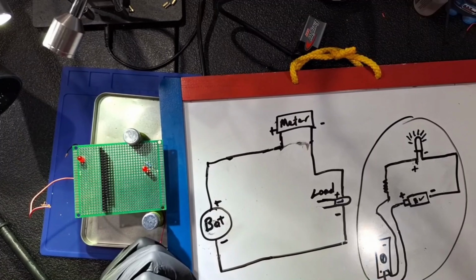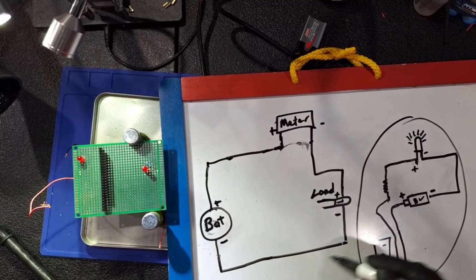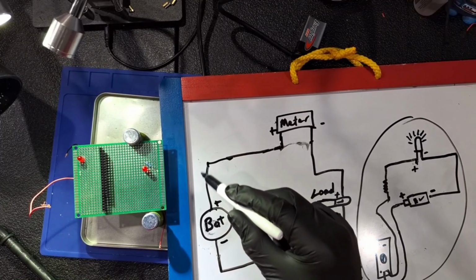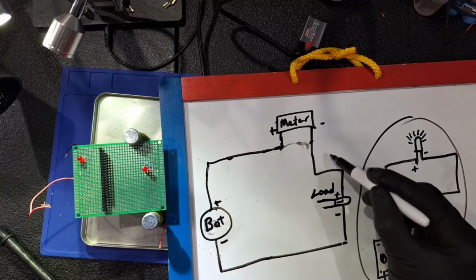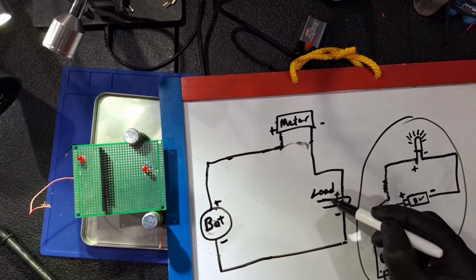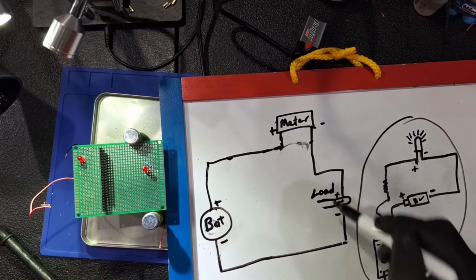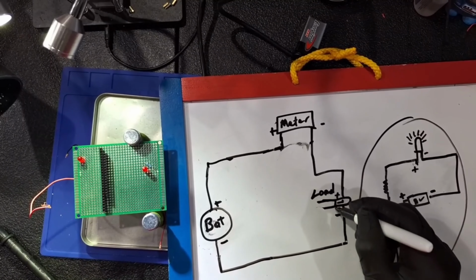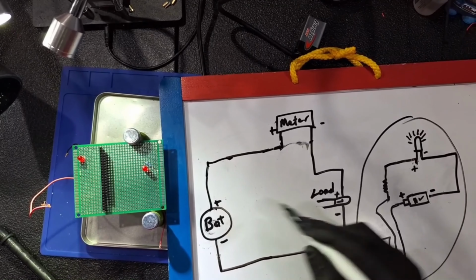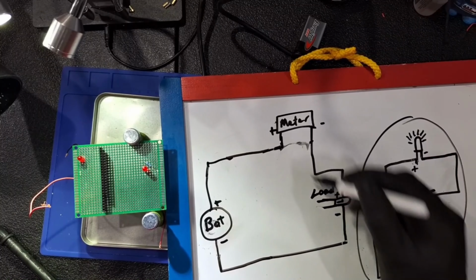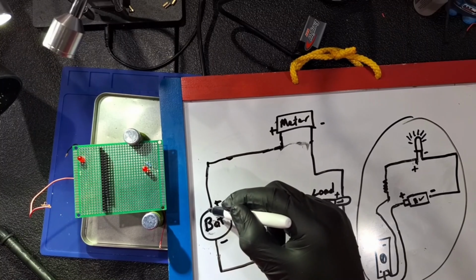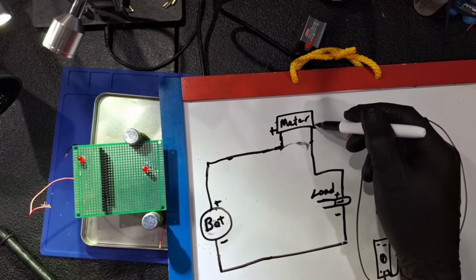And this is what was confusing me, mainly because of color codes. I was matching black to black, red to red. Before I did the diagram to make it simpler, I was saying the black probe should not be going to the red on the LED. Black should go to black. And again, I think that's a simple mistake that a lot of beginners make. But looking at this diagram, it's pretty straightforward, and this is how you properly break the circuit so that the current runs through the multimeter to get the amperage reading.